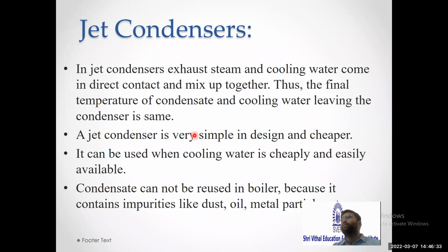A jet condenser is very simple in design and cheaper. It can be used when cooling water is cheaply and easily available, in case of sea, etc. Condensate cannot be reused in boiler because it contains impurities like dust, oil, and metal particles.